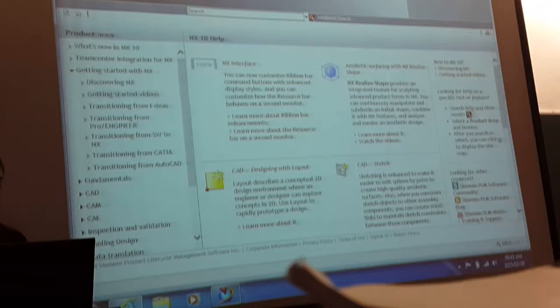Put an arc in place there, and then it automatically goes across back to that straight line option. You can choose, obviously, as you move the orientation, the line goes through the various snap orientations, so we can snap to a vertical line for that, so let's do that. Cross again here, and then over to our original starting point. Okay, press escape twice to get out of the feature. Okay, there's our part, we're happy with that.